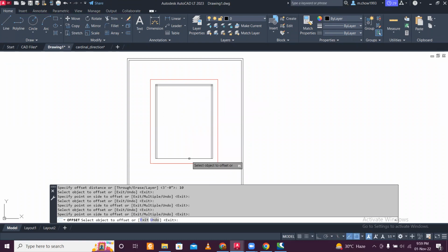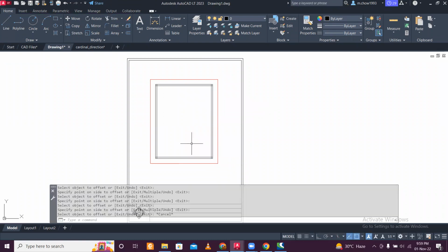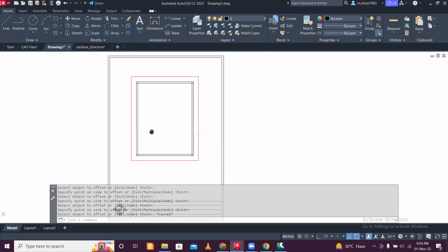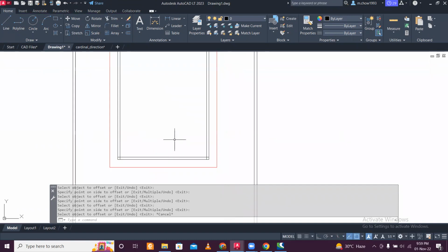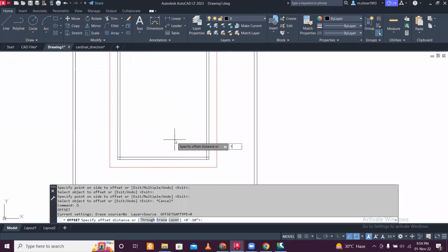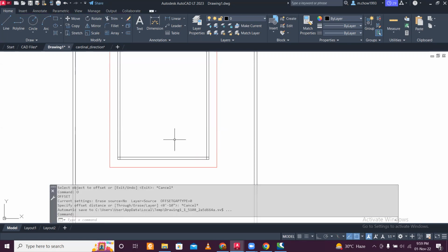So RCC building. The outer wall I'm taking as 10 inches here. Let's take 14 feet of space here for the garage, and first of all let's plan the staircase from here. For planning the staircase, let's give a tread of 10 inches, and a staircase width of 3 feet 3 inches.